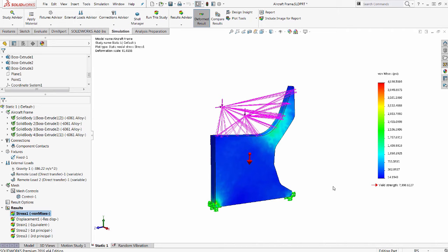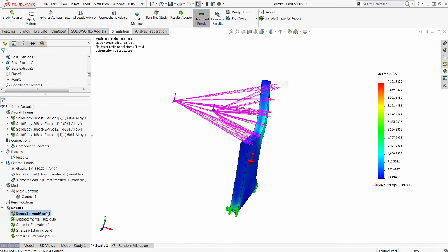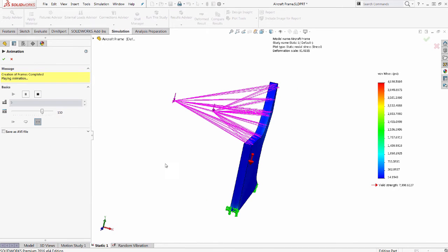So anytime you're using any numerical analysis tool, you're using a CFD tool or FEA or SolidThinking for that matter, it's always recommended to have an idea, an intuition of what you expect from the results. For example, one way to confirm your intuition is by looking at an animation of the deformation. So here is an animation of how your FEA analysis looks and what is expected. Needless to say, this is magnified about 92 times so that we can actually visually see it.